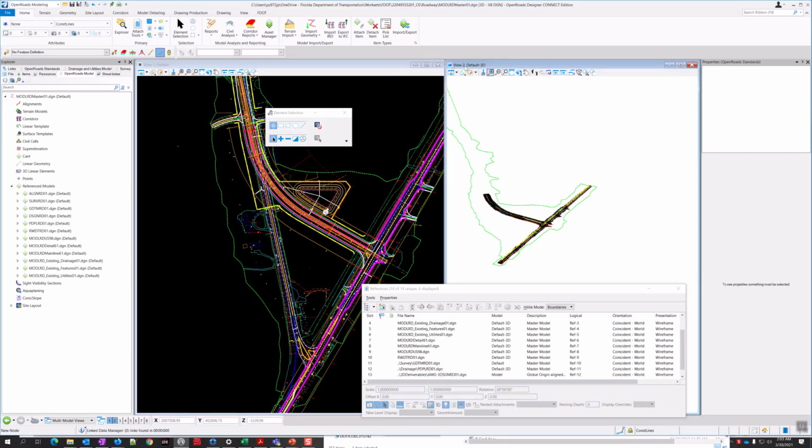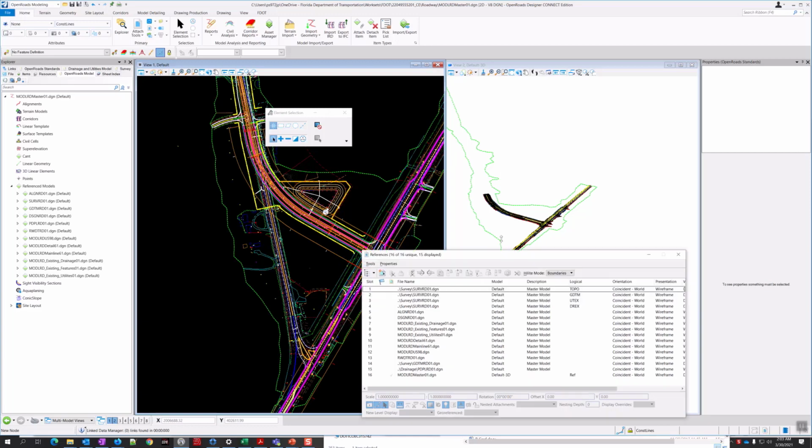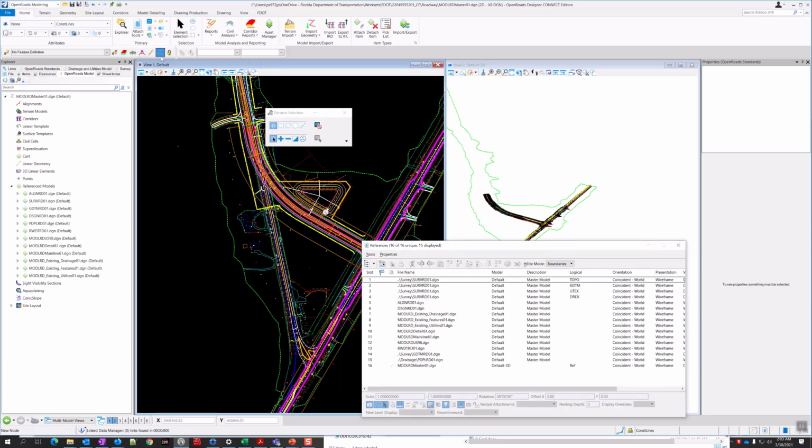Alright, so if your 3D view is active, you want to make sure your 2D view is active first. And step 2 here, we're going to attach the AMG 3DSGN01 and the AMG 3DSGN RDEW01. So the two files that we created in the 3D deliverables chapter, we want to attach them in the 2D view. Now they're 3D files. You might think we'll attach them to the 3D view, but we actually need them attached in the 2D view for this to work.